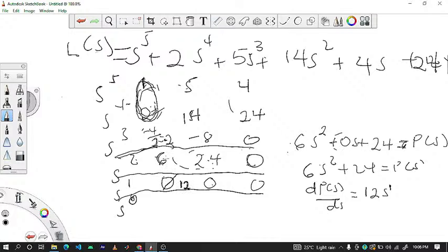So what you have to do is replace this 0 with a 12. Like I said, this has the s squared, this has the s to the 1, so you replace it with 12. And then you continue the Routh-Hurwitz criterion the same way you do it. So from here, you do 12 times 24 minus 6 times 0, divided by 12. So here will be a 24. And when you get this, you are done solving the question.